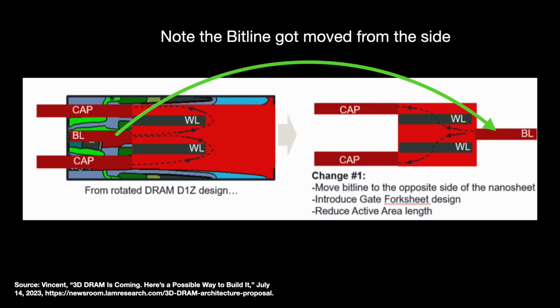Lam also made the access transistors gate-all-around transistors. These are leading-edge structures that do a better job of controlling the current. This helps retain gating performance. The architecture that they ended up with kind of looks like a strange Lego pine tree, or this one building in Taipei's Neihu district that I bike past a lot.